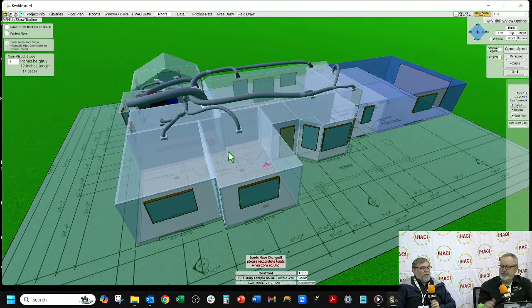Yeah, that's short cycling. It's blowing really cold air into the room, and then the system shuts off. The thermostat doesn't have a chance to even see what's going on in the rest of the house. Oversized equipment has been a big problem. So we'll finish with heat pumps.